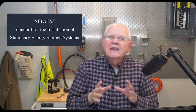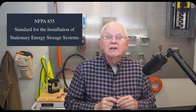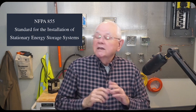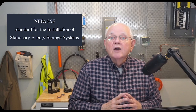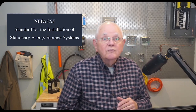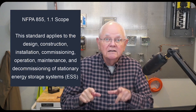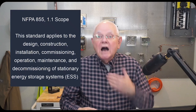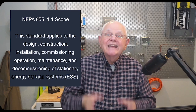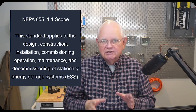The NFPA 855 standard is the standard for the installation of stationary energy storage systems. It has a lot of information. But let me review a little bit of the information with you on battery safety from the NFPA 855 standard. First of all, the standard itself says it applies to the design, construction, installation, commissioning, operation, maintenance, and decommissioning of stationary energy storage systems.